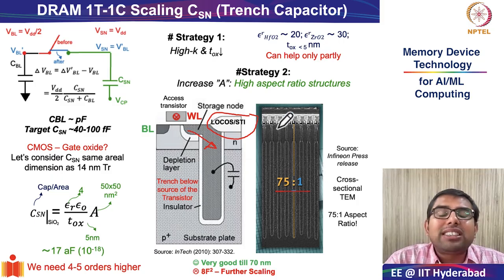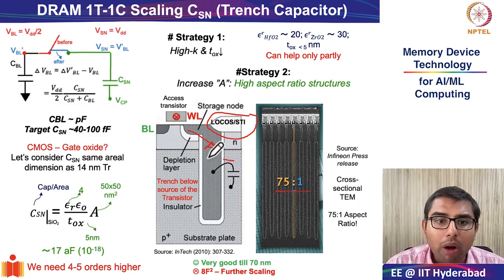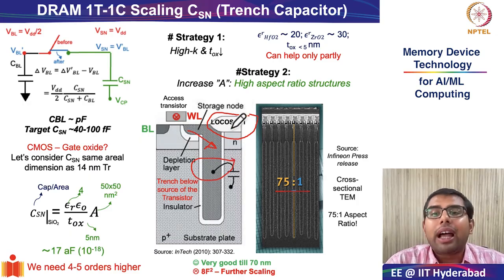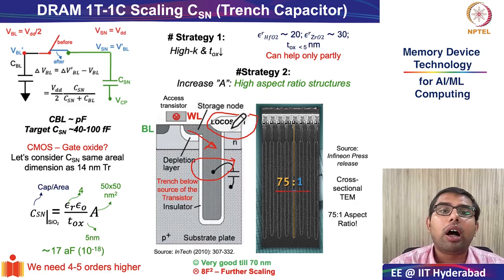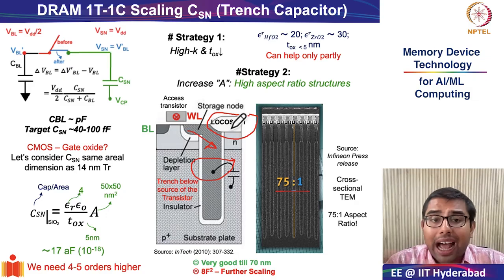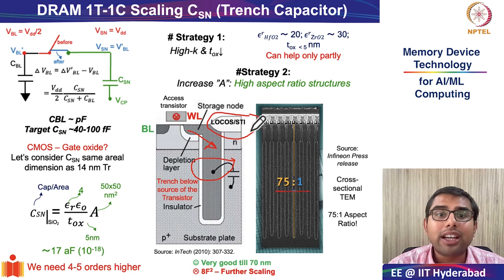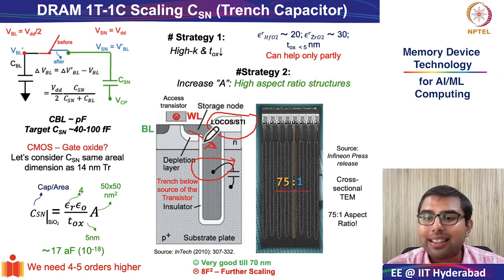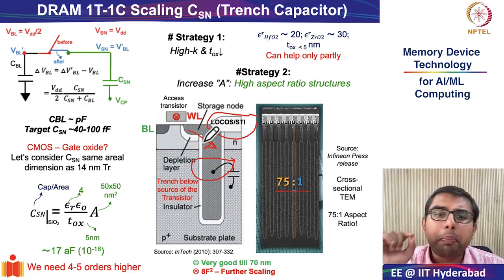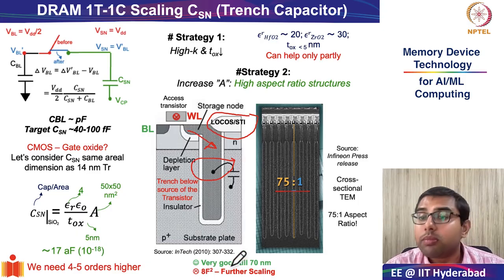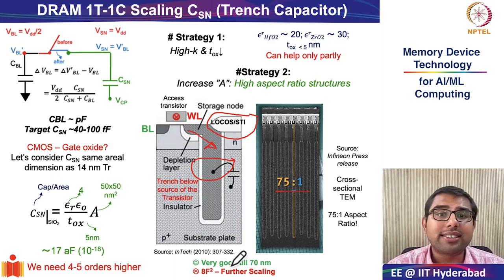So you have to maintain some space because you have to accommodate the trench capacitor also, and you have to give some margin for making sure of isolation, so that there is very little cross coupling between neighboring cells. And this is why there is a prohibitive 8f squared scaling rule, which is only possible when you come to this technology of trench capacitor, right?